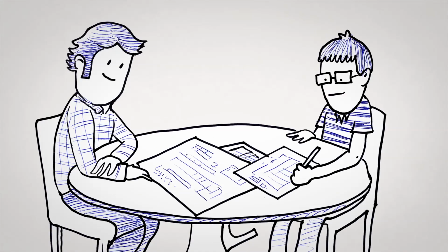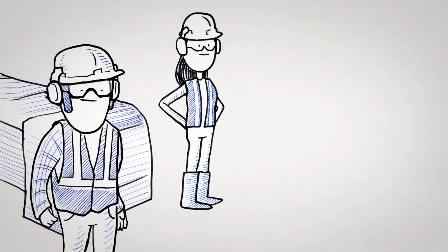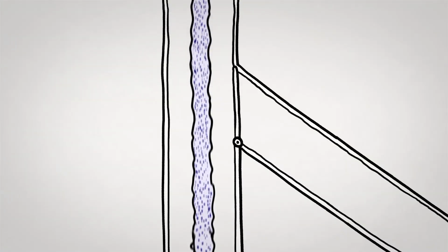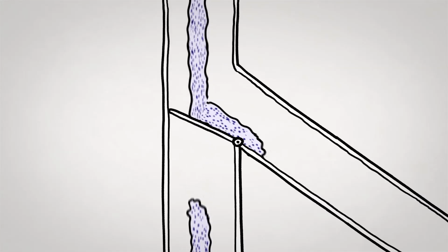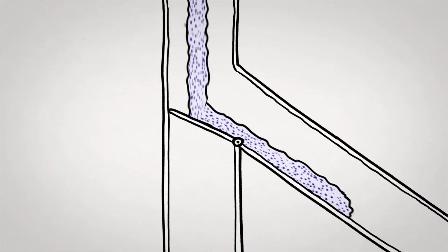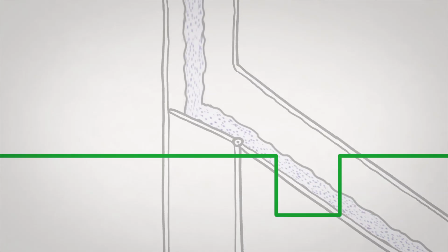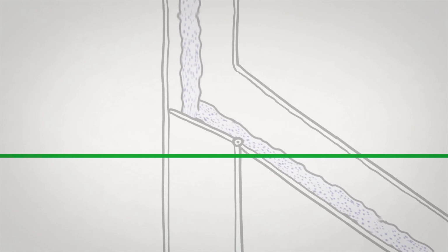After discussing sizing and design with the manufacturing technology team and vendor, the team completed the MOC, or Management of Change process, and was able to apply a short-term solution to slightly increase the speed of the leg. Once completed, the finished meal was removed fast enough so that it didn't back up. They fixed it. A plan was made to permanently increase the size of the leg. This solution tackles the root cause at a bottleneck and will prevent it from happening again and becoming a reoccurring dent.